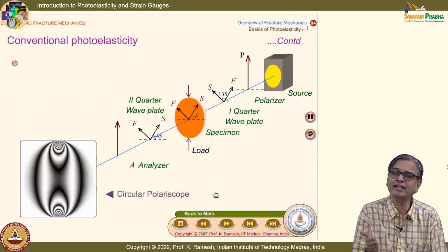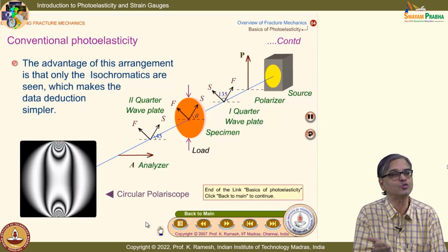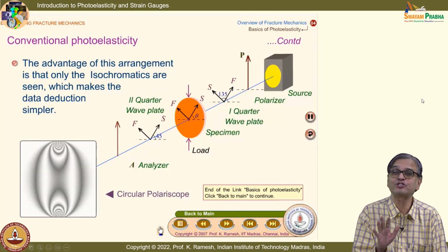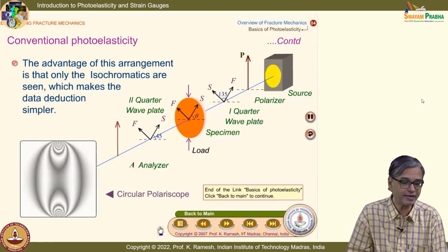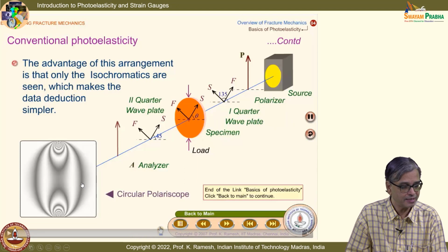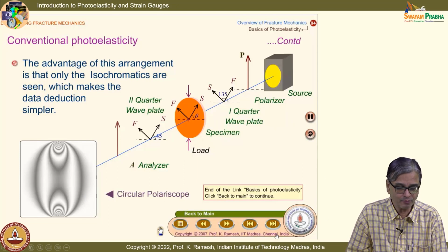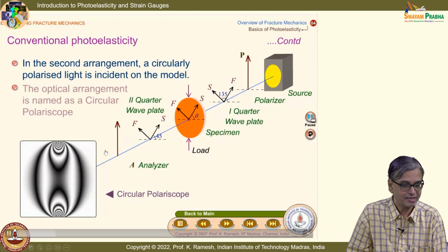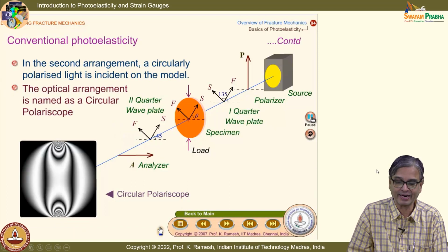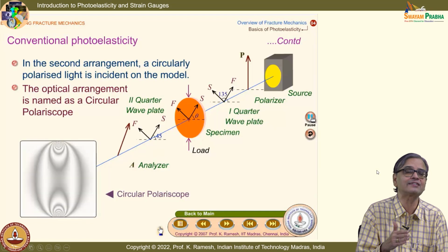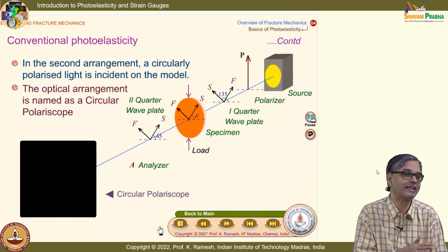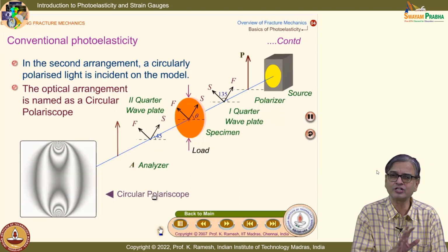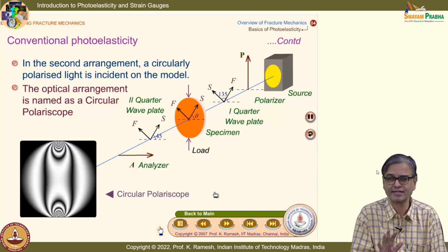It makes my measurement very, very comfortable and easy. In all my earlier slides, I have used only this arrangement to show you fringes. I have not used the monochromatic light source, but the white light source. When I use a monochromatic light source, I will have only black and white. And you can also see one more thing: if I have the background as black and I rotate the analyzer, the background becomes white. They are respectively called a dark field and a bright field arrangement, which you can do by manipulation of the optical elements. So those are all the details with respect to photoelastic analysis.